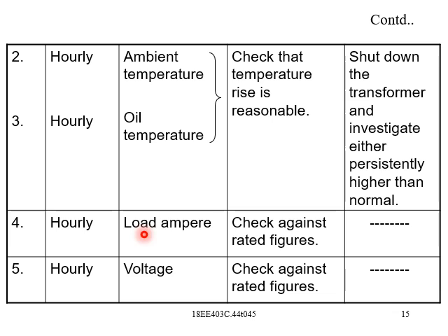So there won't be a huge cross section or a smaller one; it just depends on the value of the current. So the conductor size depends on the current, and similarly there will be some insulation parts in the transformer. The value of insulation is according to the value of voltage. So insulation depends on the levels of voltage involved.